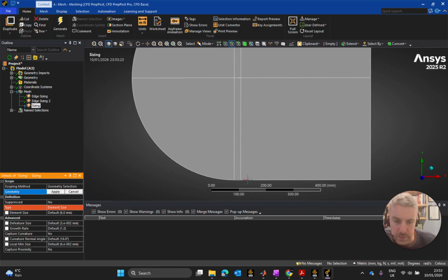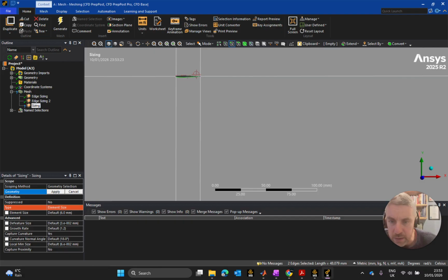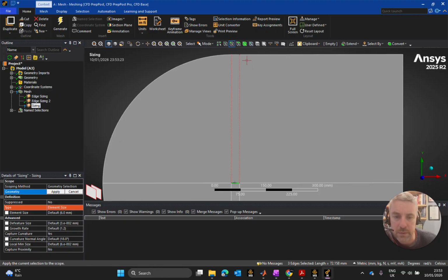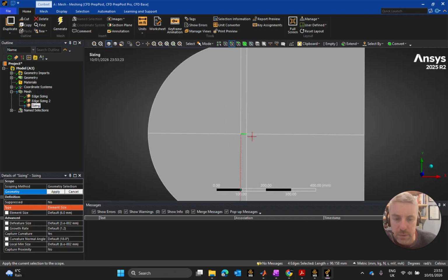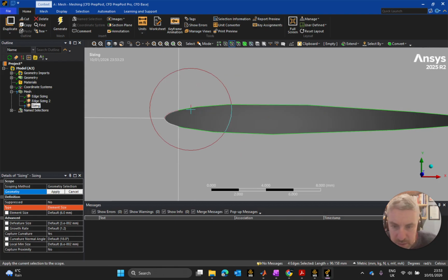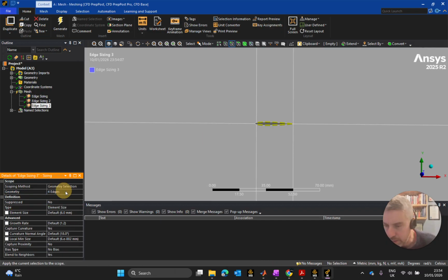Okay, next mesh. Right, let's insert another sizing regime. So the geometry is going to be the top of the airfoil, the bottom of the airfoil, and the top one up here as well. What's going on up here? There we are, 4 edges. Oh, no, I'm just going to come on into the airfoil so you can see what I selected. So it's just the lines at that aftmost point on the trailing edge to this line here, not these front ones, just the ones on the top and bottom of the airfoil, excluding the ones approaching the leading edge. Okay, apply them 4 lines onto it.